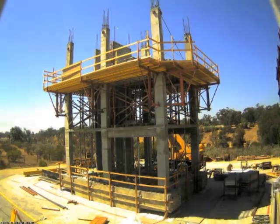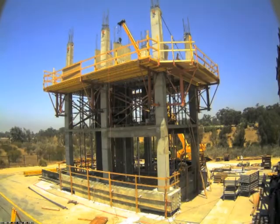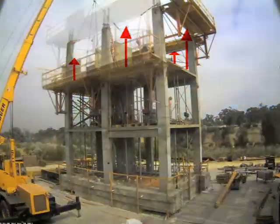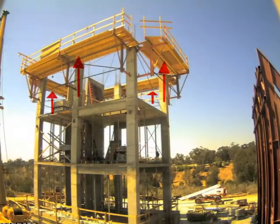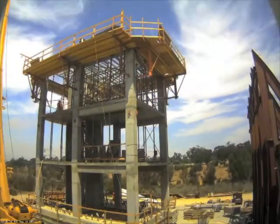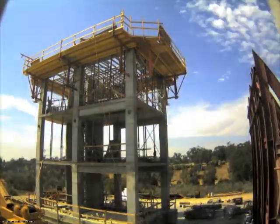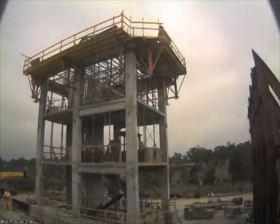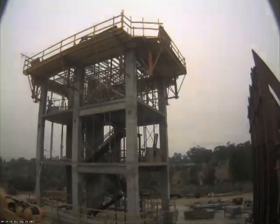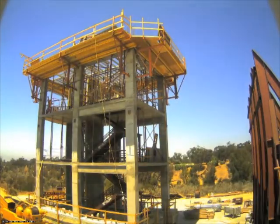After finishing the second floor, the formwork for the shear walls and columns was removed. Because of the repetition of the procedure, system formwork is used for building the rest of the floors to decrease costs and increase the speed of construction. System formwork is made from standard modular components that are assembled like Lego pieces. In comparison to conventional timber formwork, system formwork has better casting quality, more recycle times, and faster erection.